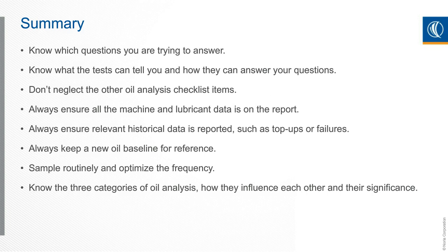And you don't want to sample too infrequently, to where the period between when you start seeing that root cause or that incipient failure and the time of the actual failure falls entirely within the sampling interval, and you never got to see the actual result. And then know the three categories of oil analysis: fluid properties, contamination, and wear debris, and how they influence each other and what their overall significance is. You want to see how that plays a role in all the various areas of the oil analysis report.